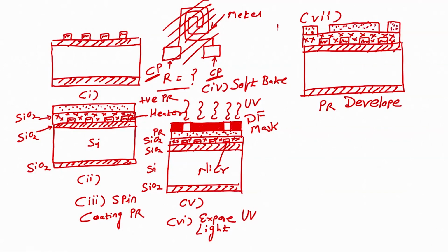in this particular fashion. Photoresist, SiO2, this is your heater, this is again your SiO2, this is your silicon and this is your SiO2, right. After that, what is the next step? You see photoresist is protecting the rest of the area of the heater except the contact pads,